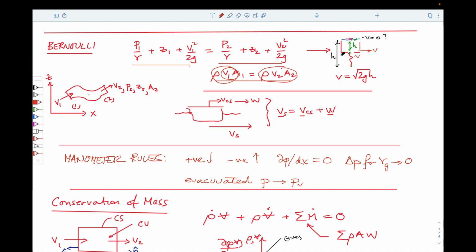If we want to, for particular geometries, we can calculate the equation for a free jet just by writing the equations for a velocity on the surface and a velocity at an exiting free jet. If we do that, we get this particular expression. The assumption usually is it's a big tank, and therefore the velocity on the surface is equal to 0, in which case we end up with this single expression.